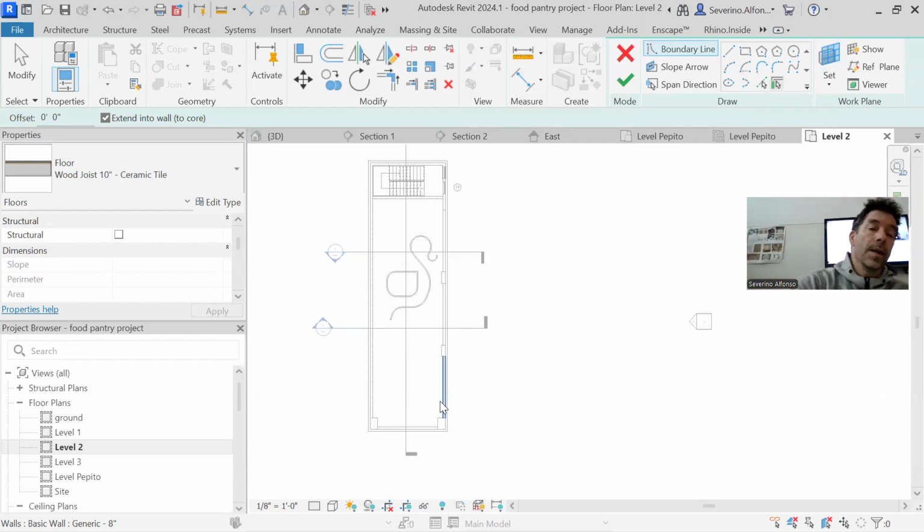And the idea, again, is that vertical things won't have the X and the check, but they will have what is called the draw options here, because you're drawing where the walls are. But with floors, it's different. It's a bit more of, hey, first, draw the perimeter of the floor, and then say, check, you're done. And it creates the floor. You did all that for us, like creating that model, you're like, I'm going to do the floor, and you put all that in.